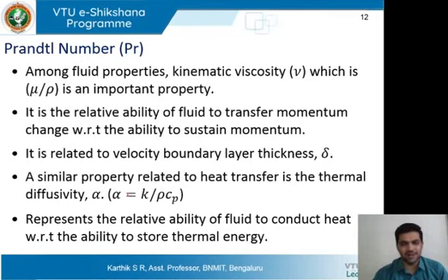So what is kinematic viscosity? It is the relative ability of the fluid to transfer momentum change, with respect to its ability to sustain momentum. If you see the ratio mu by rho, mu, the viscosity, conveys to you how the momentum disturbance at the wall is being transferred to the layers above the wall.